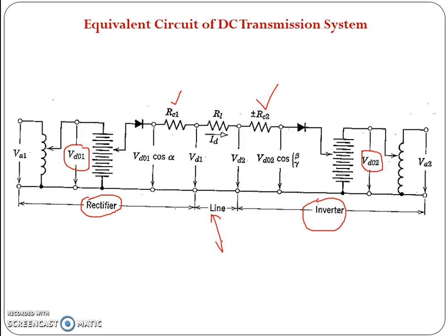When considering the desired features of control of an HVDC system, the first is limitation of the maximum current so as to avoid damage to valves and other current carrying devices. That means the maximum current carried by the devices or valves should be under control. The second is limitation of the fluctuation of the current due to fluctuation of the alternating voltage. There may be chances of commutation failure as well in the cases of switching the valves. Also there is a requirement of prevention of arc back of the rectifier valves. Another important desired feature is to keep the voltage at the sending end of the line constant at its rated value, so that losses are minimized for a given power. The other important desired feature is controlling the power delivered, or in some cases the frequency at one end.